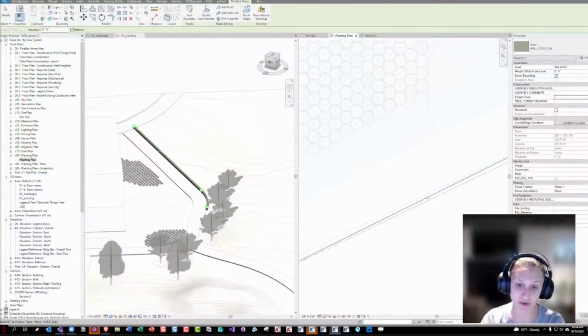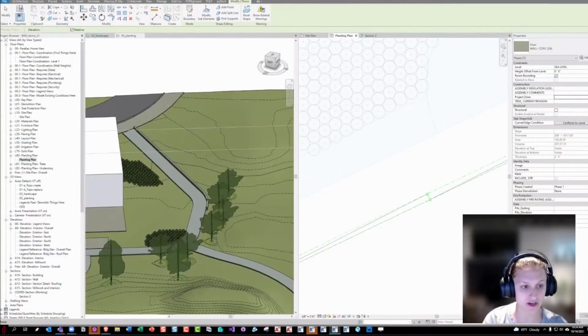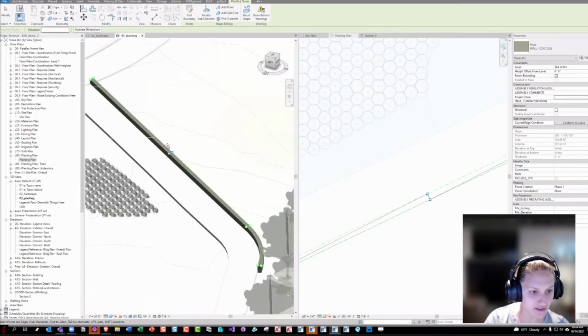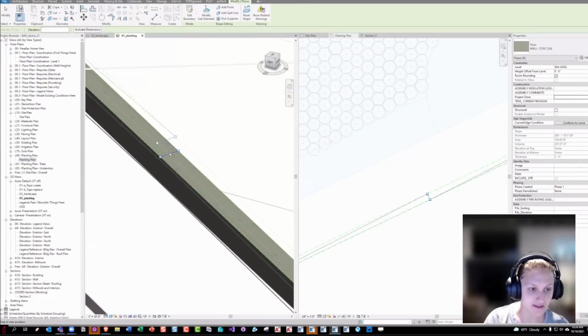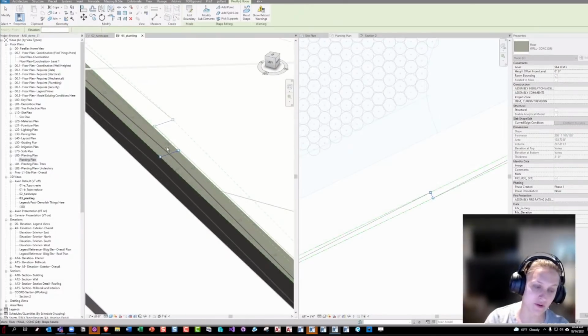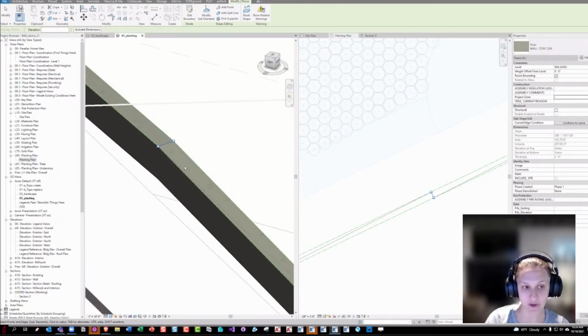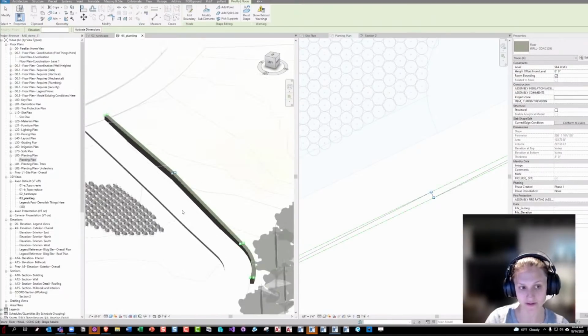And here is kind of nice because you could use the points to modify that at the really wonky site areas and make it a smoother transition. Or if you wanted it to do all sorts of crazy stuff, like here, you wanted this to be up, you could drag that point. You would need a deeper wall, but you can start to sculpt your wall, which is how landscape architects typically work with walls.